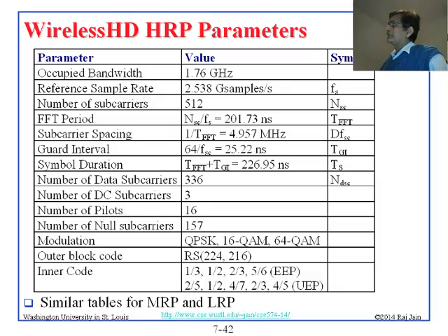But I haven't explained DC carriers. I want to explain DC carriers, and then these are the null carriers, and these are generally at the end. They could be in the middle too, but generally they're at the end. These are the guard carriers. So these protect you from the neighbors anyway. So DC carriers. Generally you have one DC carrier, and DC carrier is right in the middle. Basically when you have this much band, right in the middle is your DC carrier, so that way you figure out where your middle is, and that is generally sent as a null.